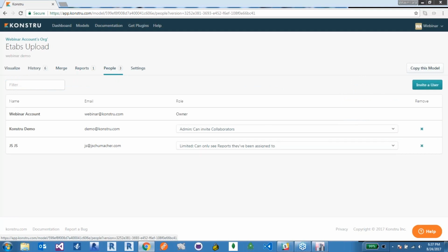we assign that element to a group, or in Revit it would be a selection set. So if I were to download the latest model into Revit, there would be a selection set for modified elements and a selection set for added elements. So I can see what has been added since the last time that I synchronized. So if I don't want to use the web interface to look at changes, but want to use Revit or Etabs or SAP or Tekla, I can also do that by using the groups and selection sets.